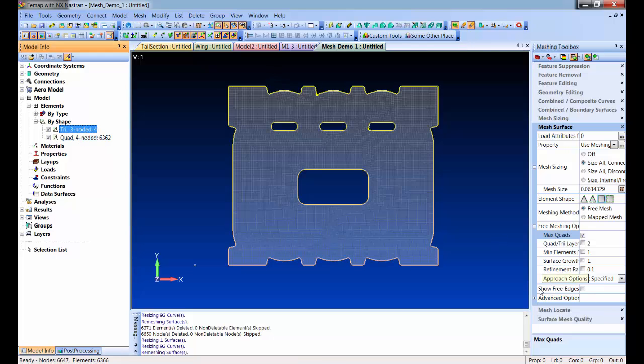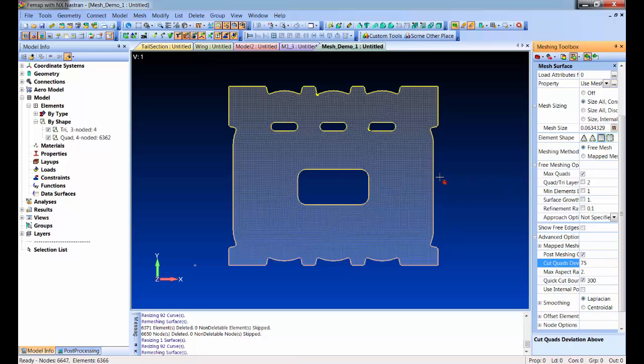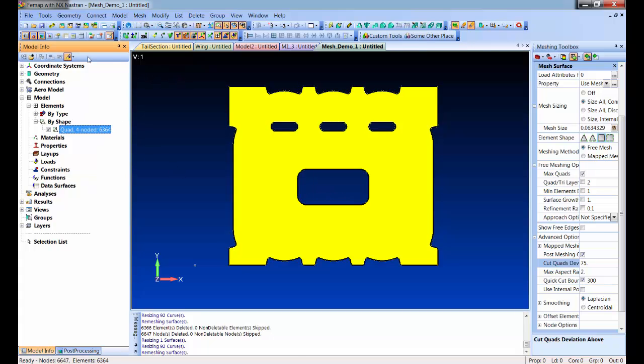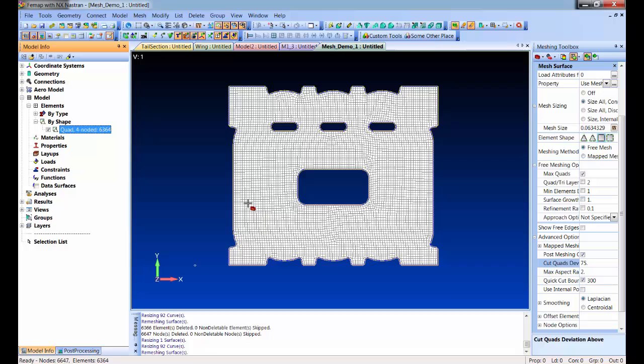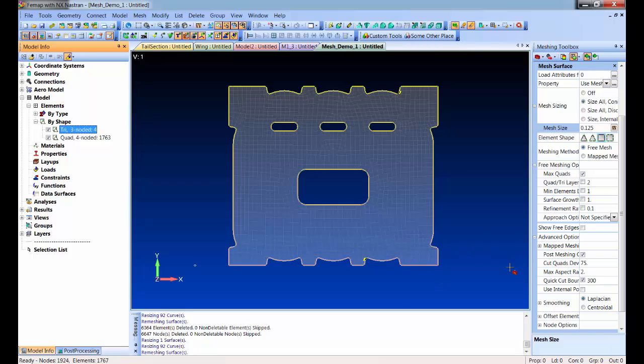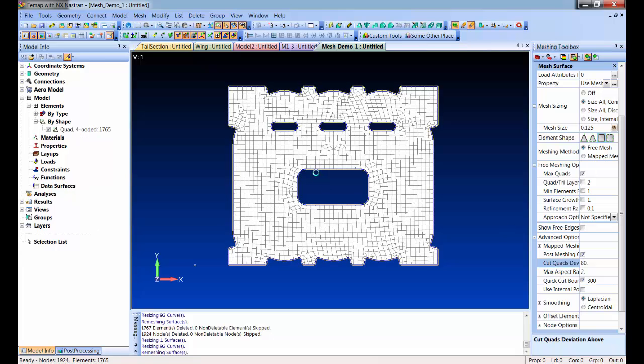Now, it still honors the maximum aspect ratio. So as long as you tune that up a little bit, you can then go to no quads at all. Turn up the highlighter. And if you change the mesh size, let's just see what it does here. A couple triangles. But again, those are along the same thing. If you allow it to get a little looser on what it'll take as a quad, you can get all quads.